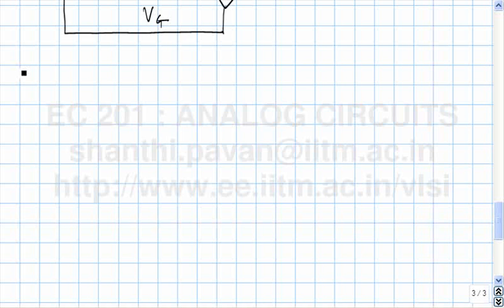As I said, having the PMOS device is very nice because the NMOS device acts like a current sink, so it will suck current out of a node. A PMOS device will act like a current source, it will push current into a node. So they work very nicely, and it is possible to make NMOS and PMOS transistors on the same chip, and this technology is called CMOS technology. And it turns out that in practice the mobility of holes is less than that of electrons, so mu p will be much smaller than mu n. In fact, typically it's about a factor of 3 smaller.